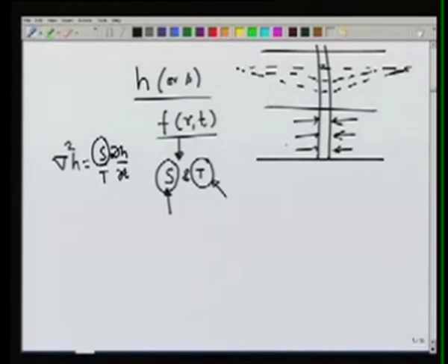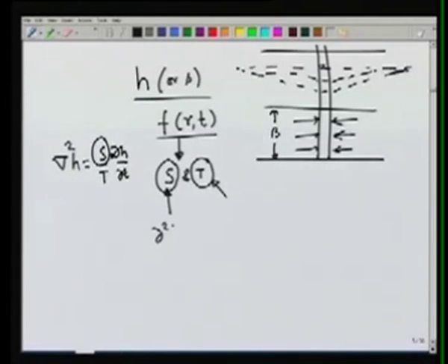So we have a fully screened well, constant thickness of B. The only assumption which we have now relaxed is that instead of being a steady state flow, the flow now is transient, and therefore the drawdown and the H will both depend on time also, and therefore the equation governing will include the transient term del H over del t.